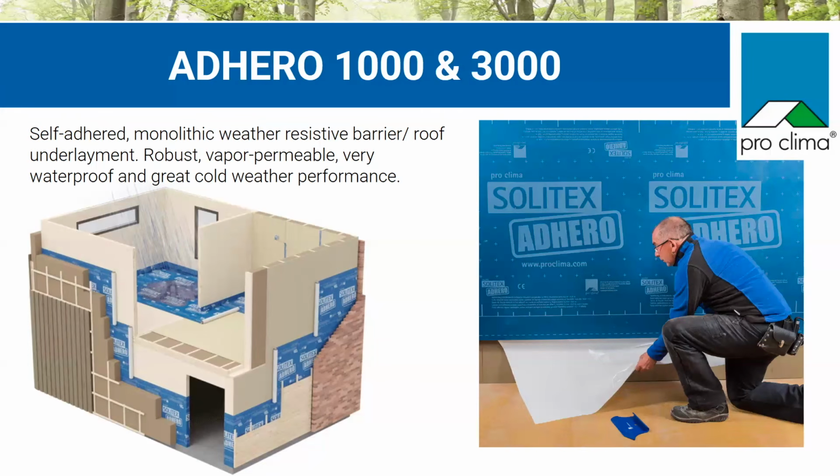So the 1000, that fleece is less robust, with lower UV exposure. You probably don't want to walk on it as much, so we're only using it on walls, while the 3000 has a more robust fleece, longer UV exposure, and is more comfortable walking on. So this is what we're waterproofing and air sealing the exterior side of the sheathing with: this house wrap, this water resistant barrier from 475.